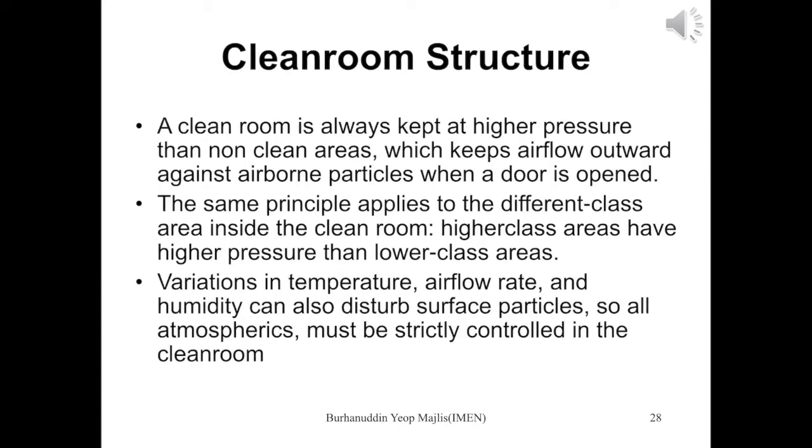A clean room is always kept at higher pressure than the non-clean area, which keeps airflow outward against airborne particles when the door is open. A little bit higher, not too high, a little bit higher than outside or other non-clean areas. The same principle applies to the different class areas inside the clean room, because we have a clean room in the clean room. So a higher class area has higher pressure than a lower class area in the clean room.